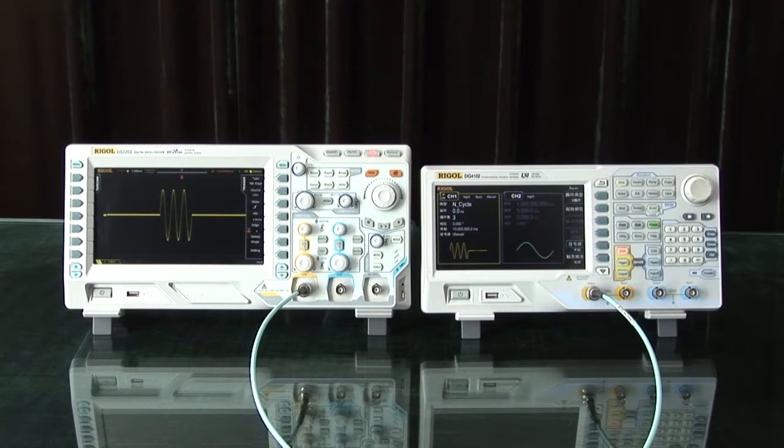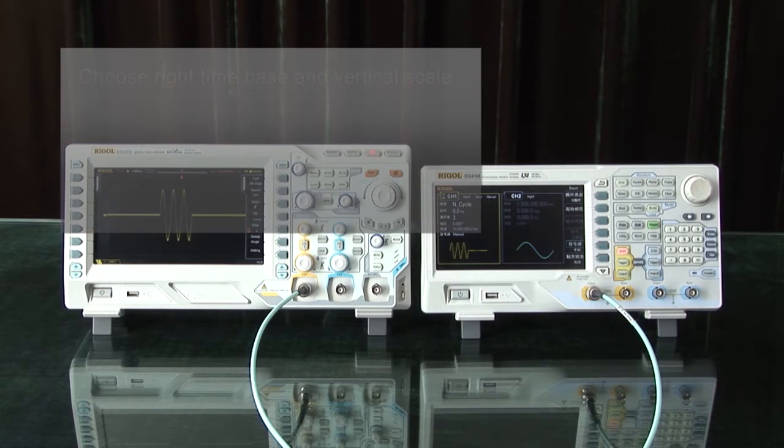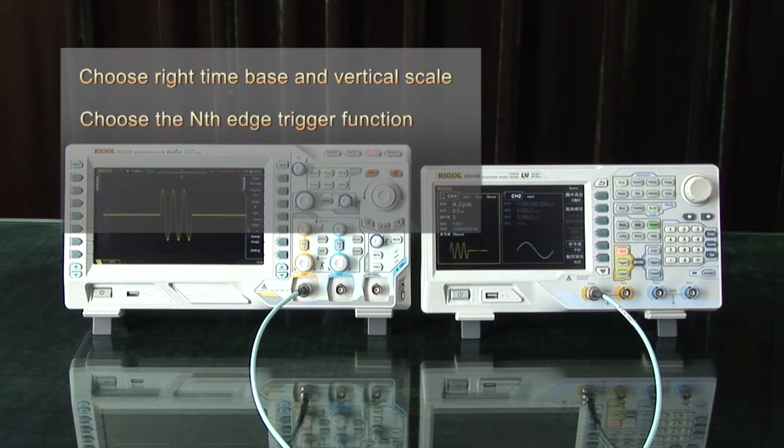Here are some key points when using the nth edge triggering. Choose the right time base and vertical scale. Choose the nth edge trigger function. Set the parameters such as idle or edge, and capture the signal.